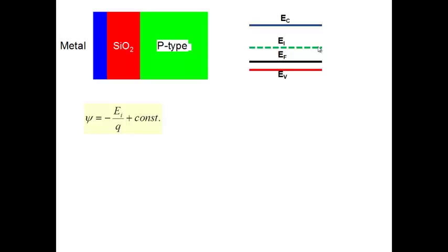Okay, both are equal, and so, strictly speaking, yes, I don't have equilibrium, but Efn is the same as Efp, and both are flat. So we continue to denote this particular quantity here as Efn. So it's as if my p-type layer remains under equilibrium. No currents are flowing.